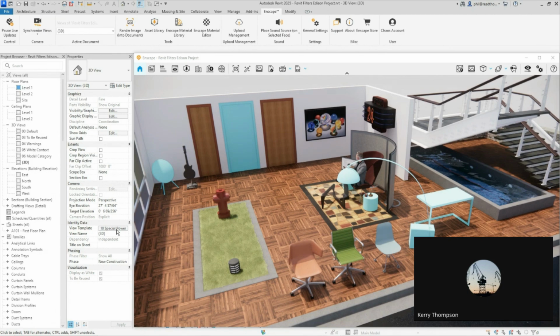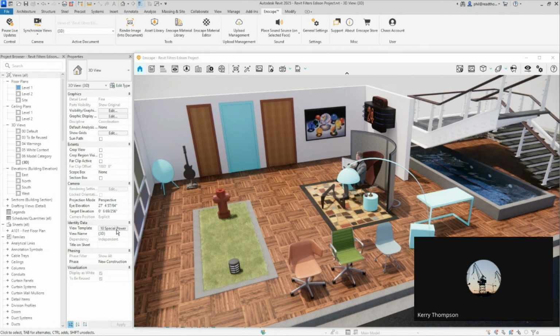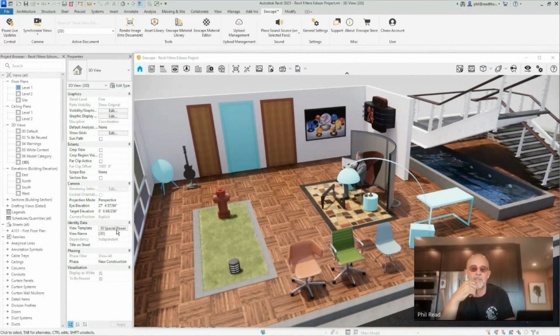So you could run a script that would recolor a whole view. When you say color, do you mean like a filter override, or do you mean a material override on a category? Material override, from what I understand, like a paint. Like you go back into the paint scenario. You know how you have the paint thing in Revit? Yeah, you just use a paint tool, but this will paint the entire object.